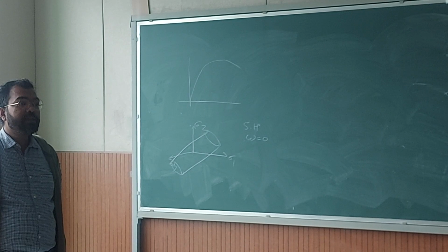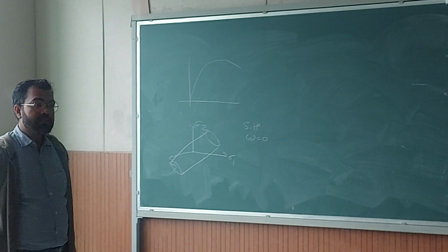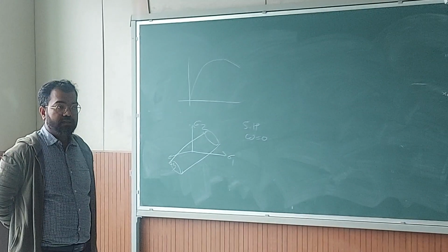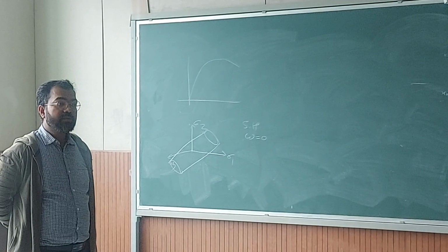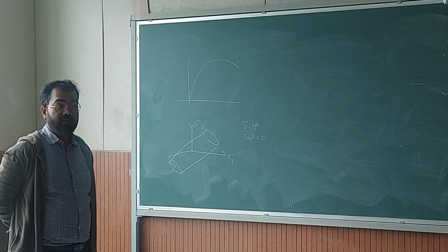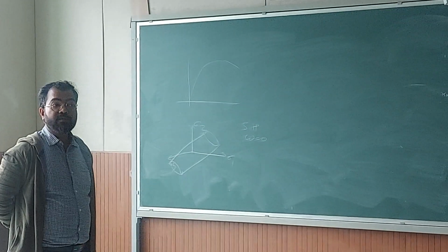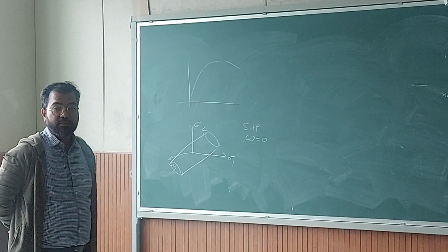Stress cannot exist at the surface, so stress goes to zero. It develops inside and it goes to zero at the surface. So the surface will be the last place where damage will initiate in monotonic loading. In fatigue, it will develop at the surface first. But in fatigue, you will not see damage. You will not see voids.